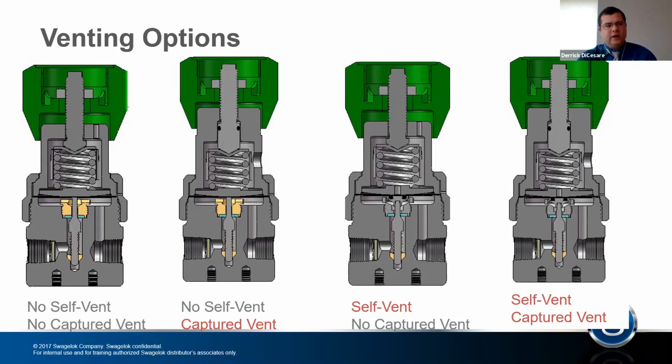When we get into the larger regulators, the RHPS series, they're all going to be an elastomer. So it's either going to be a Viton, a Buna, or an EPDM. It's going to be one of those three when we talk of really 1/2 inch to 4 inch. It goes to an elastomer diaphragm. So we want to choose one that's going to be appropriate and compatible with the system media. Our standard is X750. It's an Inconel nickel-based alloy.